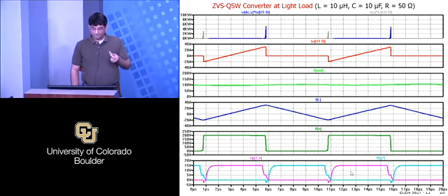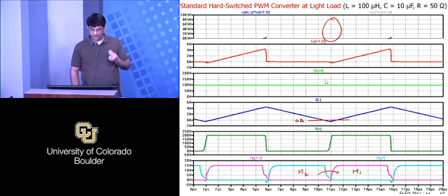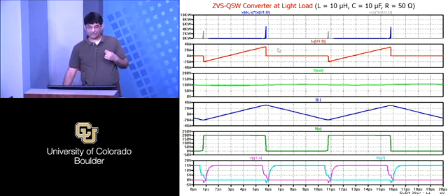In fact, this is the simulation with the quasi-square wave, and you actually see that the turn off switching losses were lower in the case of the hard switching than in the case of the quasi-square wave. Again, because you have larger ripple here, so the turn off currents are larger, and just the thing I just explained, you will have higher losses in this, right?